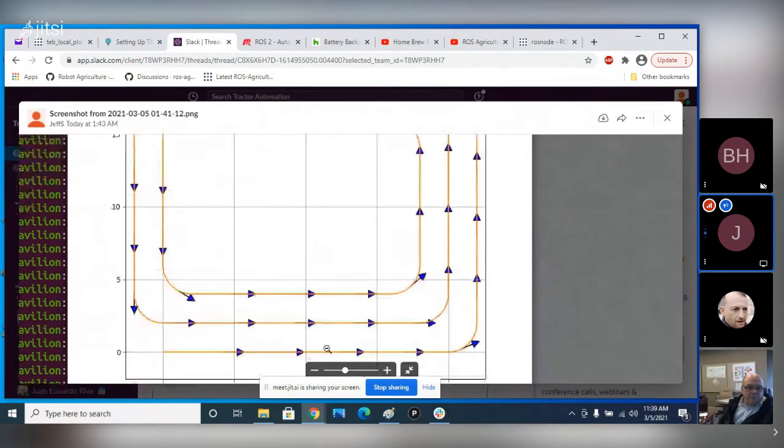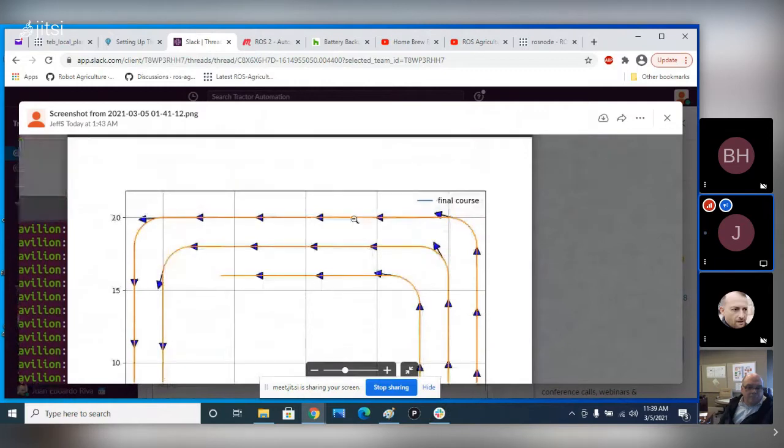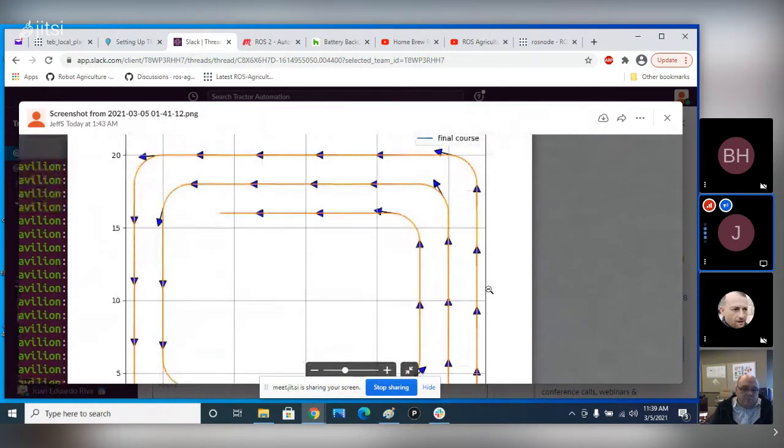So what we're going to do is define these 3 horizontal lines, and these 3 horizontal lines, and then let the Dubins path planner generate these vertical lines at the end. What controls the spacing on those is the radius that's defined in the Python program. So if you look at that, there will be 6 pairs of lines.